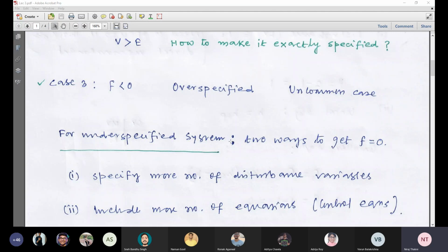You can connect now. I repeat, when we started the variable classification table, it was mentioned that the load variable, or disturbance variable, can be classified into two classes: one is measured disturbance, another is unmeasured disturbance. And at that time I mentioned that we can go for measurement of the disturbance variable as per the requirement. Now here the requirement is involved.